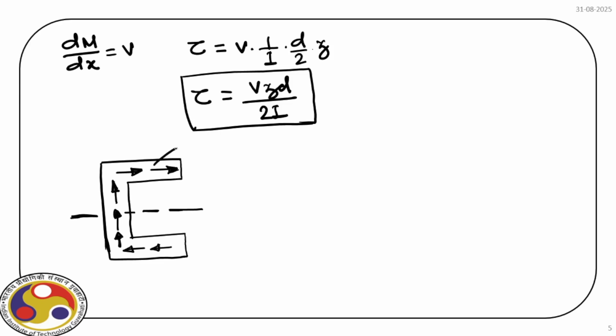these two stresses in the flange, they are equal in magnitude and opposite in direction and separated by a lever arm. Obviously, that will cause a rotation, right? That means for this type of section, if we apply, say, bending, that will cause a rotation at the section level.